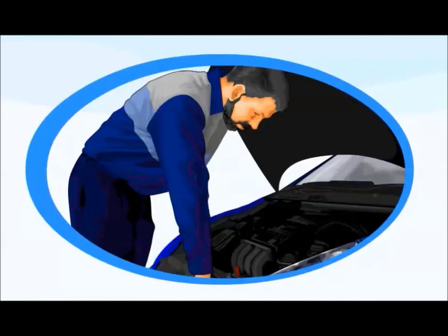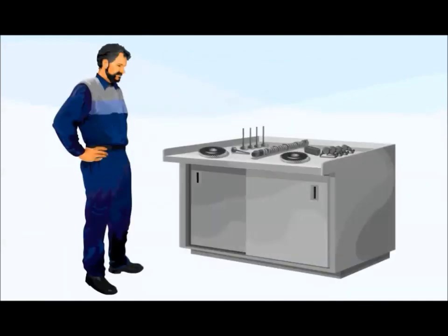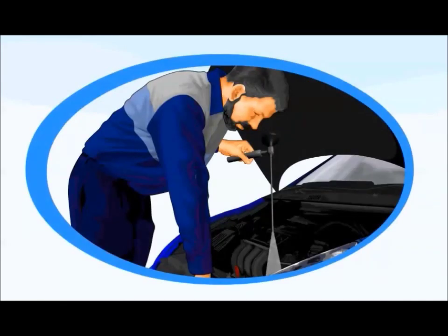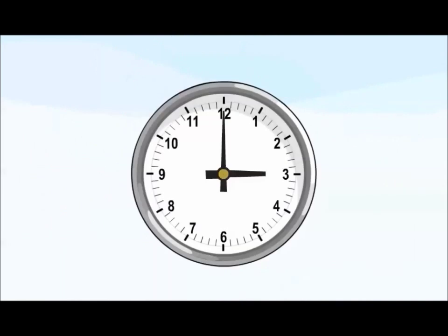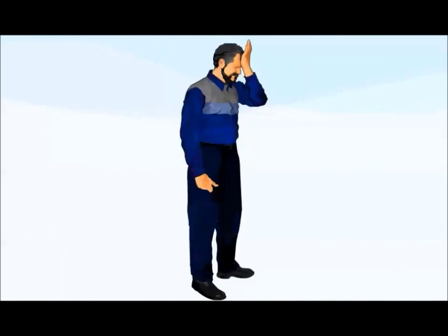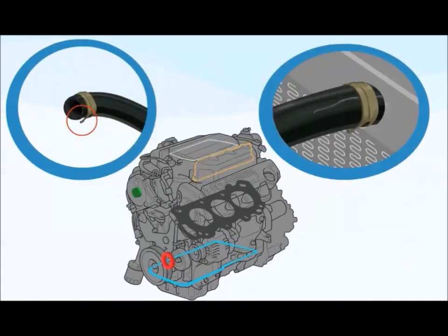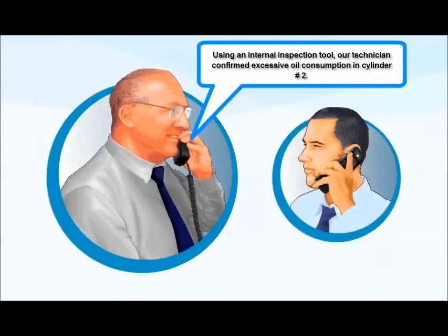Technicians always have the option to disassemble the engine to perform internal checks, but this approach is time-consuming and doesn't always locate the problem. To help prevent these problems, a tool called a Borescope allows technicians to inspect internal engine parts without disassembling the engine. A Borescope can save time, but it also avoids hassles such as broken clamps, torn hoses, and the cost of new gaskets. Using a Borescope to confirm internal problems can also help justify an engine teardown to the customer.